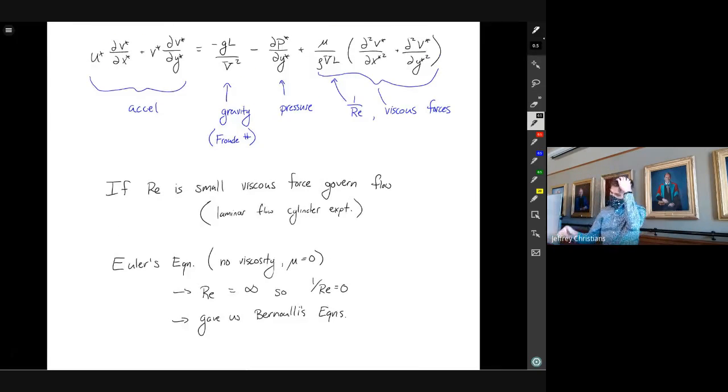And essentially we got, what does fluid acceleration depend on? How does fluid move? Well, it moves only in response to pressure gradients. It flows toward low pressure and away from high pressure, and it curves around areas of low pressure, and it curves away from areas of high pressure. And that's how we looked at forces on, like, an airplane wing.